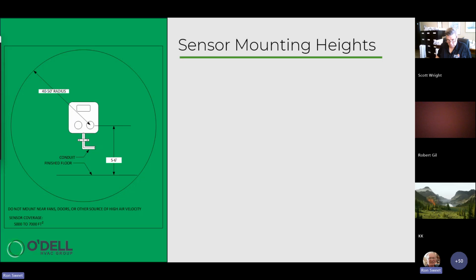Having been exposed to 90 ppm for 45 minutes, you already have a headache. You already feel nauseous. You feel like you're getting the flu. But the beep, beep, beep, and the little red LED starts flashing, and you immediately know you're being carbon monoxide poisoned. In the industrial and commercial space, carbon monoxide sensors monitor in ppm, 1 ppm right up to 200 ppm.